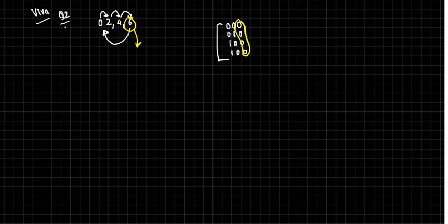After half of the Viva was done, many people were able to answer that, maybe because they had discussed with the others. So if we consider this LSB as constantly 0, 2 flip-flops are okay. We simply need to make those flip-flops count from 0 to 3: 0, 0, 0, 1, 1, 0, 1, 1, that's it. And this we can simply ground. We can consider one terminal as ground. So the complete circuit would be something like this.